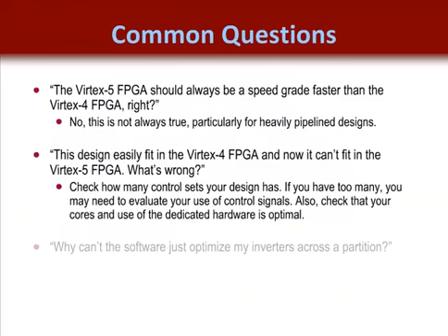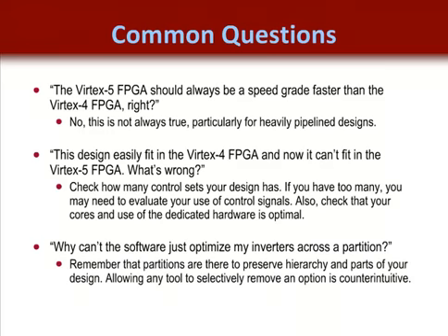Another question, why can't the software just optimize my inverters across a partition? Well, remember the purpose of partitions, and again, now we're talking about incremental design, where a designer may want to isolate logic and not allow it to change between implementations because they tested, they verified the results, the timing, the simulation, they like the results, and they want to keep it now.